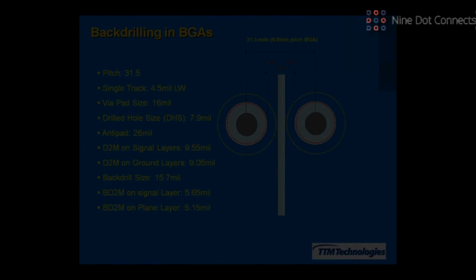Solder mask approach, we talked about that. It's always good to talk with your fabricator and make sure they explain exactly what they want. And also on the design side, that the requirements are exactly specified so folks know. This is a good graphical representation to kind of pass between people, and that way they get an understanding. I want it to look like number 2, or I want it to look like number 3, and things like that, because there's a lot of different terminology also that's used throughout the industry, depending on what part of the globe you're in, so we don't always use the same terminology.